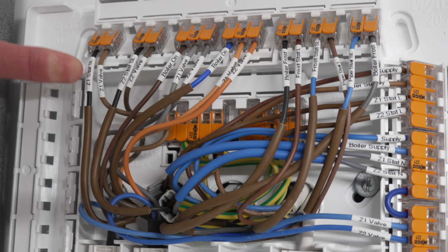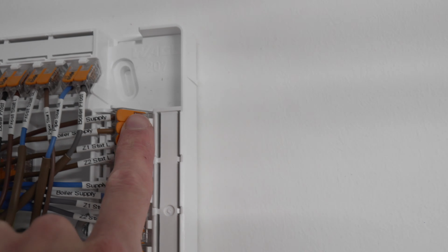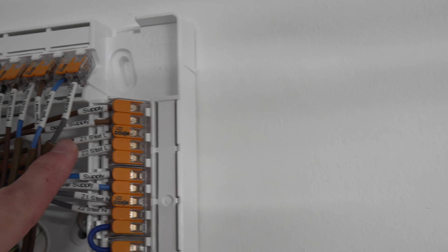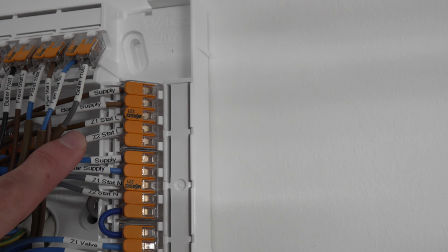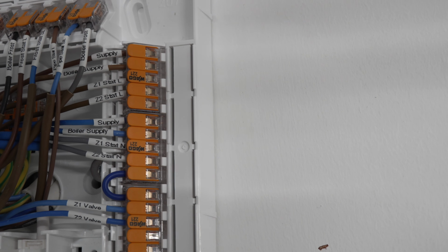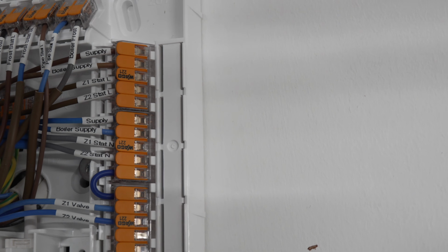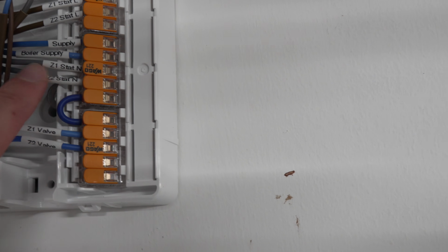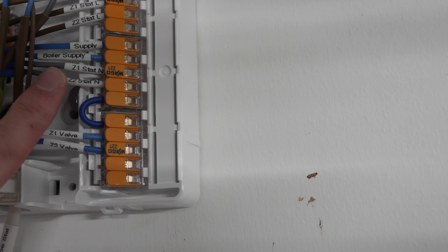We also mentioned that the brown wire at the thermostat is a permanent line. We can find that over here, so these are all the permanent lines connected together. So we've got the supply, the permanent line off to power the boiler, and we have these two here, which is zone 1 stat line and zone 2 stat line. These are the permanent lines that go to the brown wires behind each thermostat. And like before I mentioned, we have the neutrals at the thermostat as well, those grey wires. We can see those down here, even though they're not being used at the thermostat, we have those neutrals here.